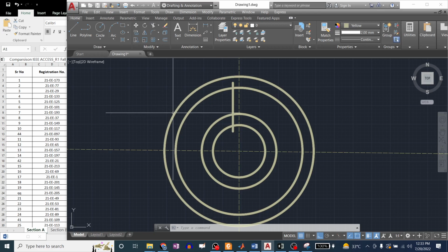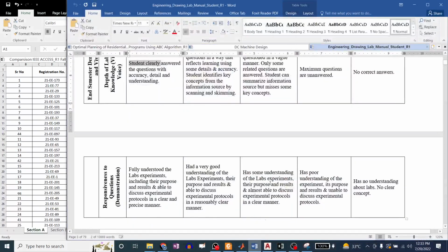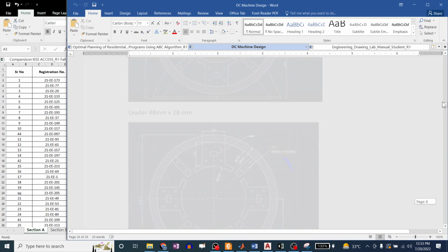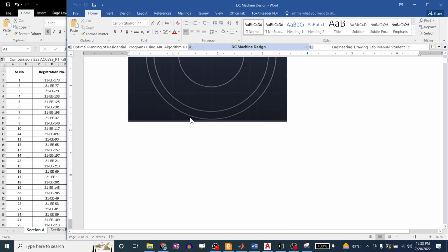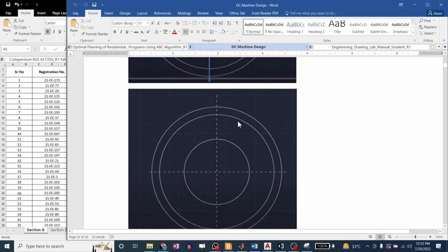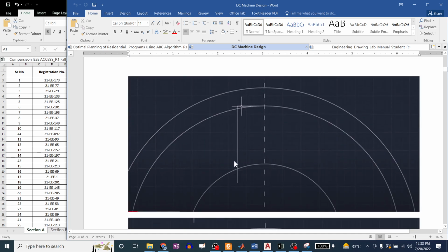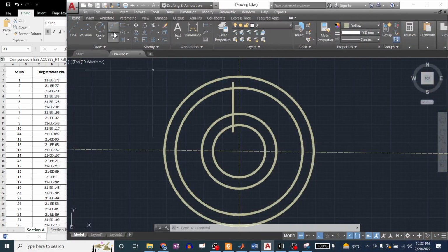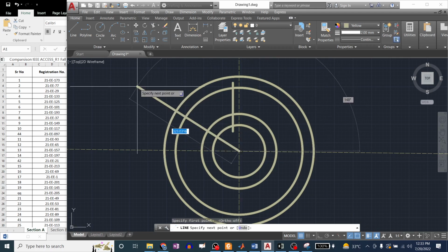Okay, so this is the line, because we want to draw this type of shape. This type of shape you can see here. If you want to start from the start, you can see two circles, three circles. These are the dotted lines, and here you can see this is the line. Okay, and then we'll need, from the center, line command, ortho should be off. From the center you can draw this line in this shape, because 200 radius, we can take 300 extra, we can trim it.